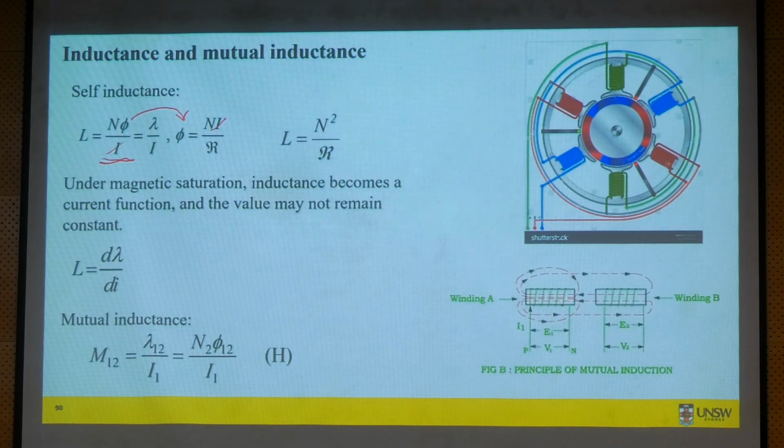Why do we have different Ld, Lq values in an IPM machine, and why do we call it the magnetic saliency? All this actually comes from the difference in reluctance in your flux path in those machines. And this can be described using this basic formula. Okay, inductance is inversely proportional to reluctance. Larger the reluctance, smaller will be your inductance.